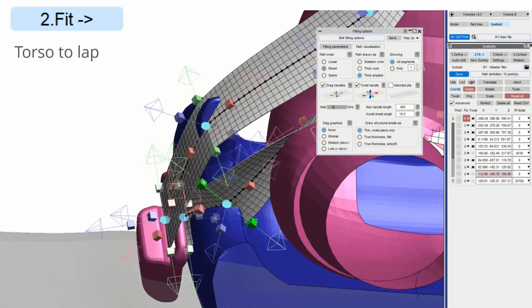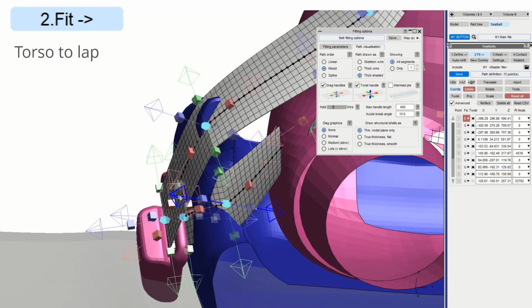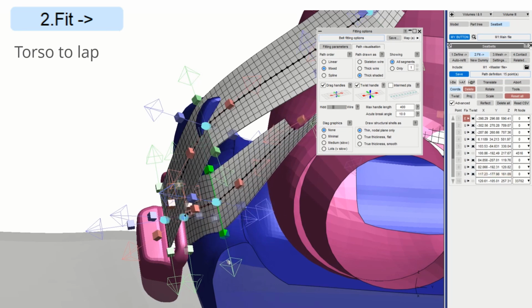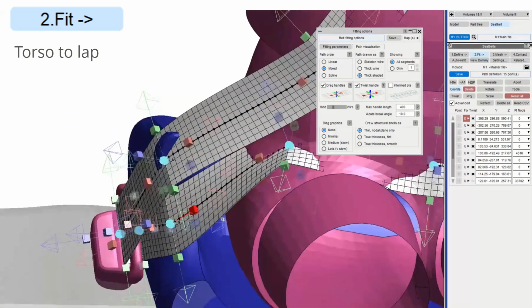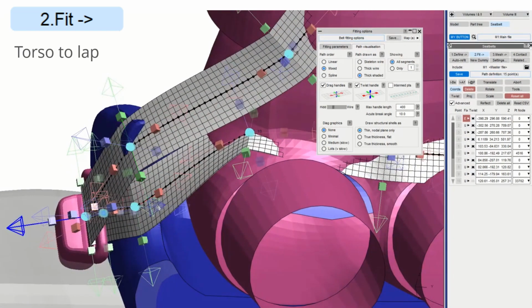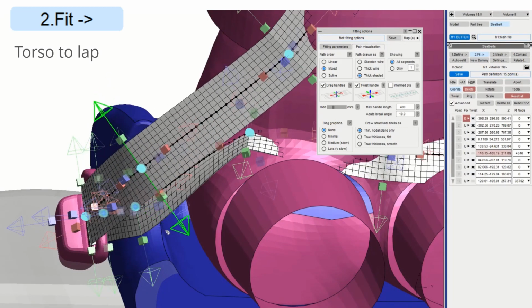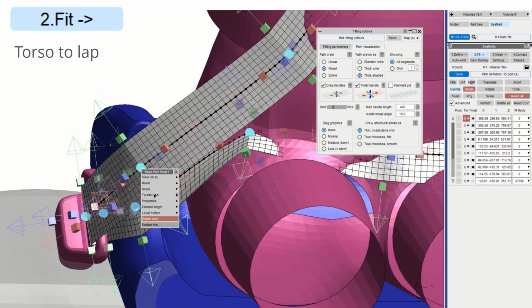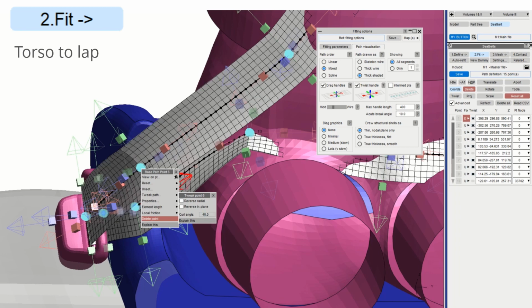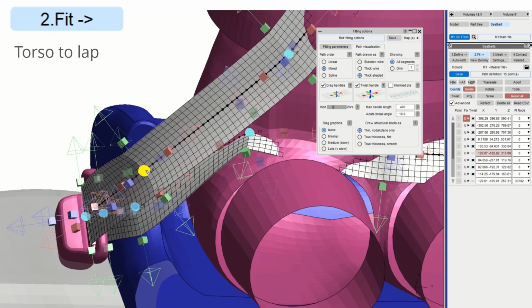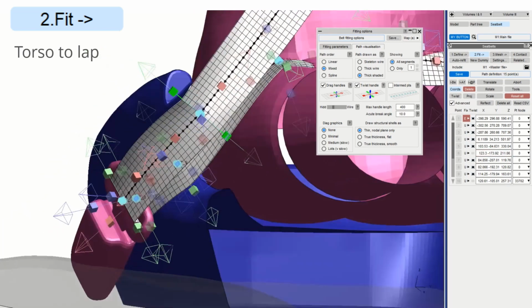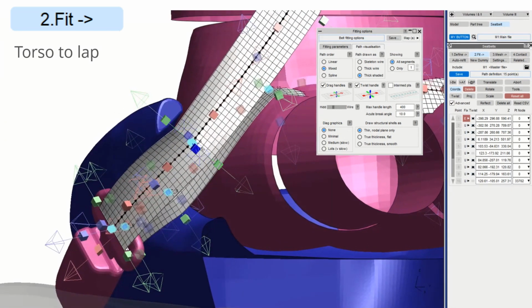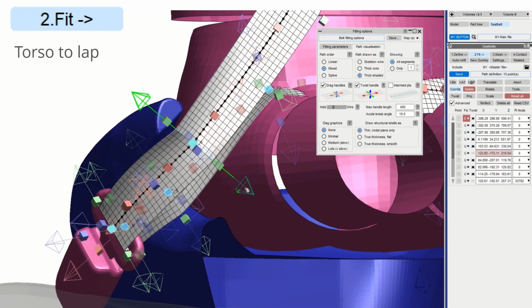So we've got 0.6 and 0.9 have to fit inside the valley of the belt guide but not penetrate. 0.9 is looking good where it is. We just need to drag and reposition 0.6, and I think it could do with some curl angle, so I'm going to give quite a steep 40-degree curl angle and then try and drag it so it can easily fit into the valley of the belt guide.